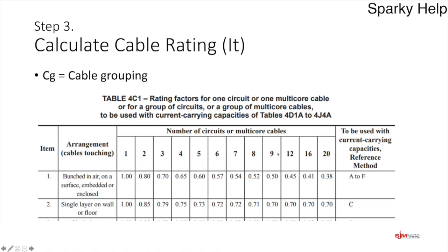And then across here, you've got a number of circuits. And remember, that is circuits, not conductors. So don't get confused when you're putting in a circuit and it's got 3 conductors with it, you don't start counting each conductor, it's number of circuits that you're installing.